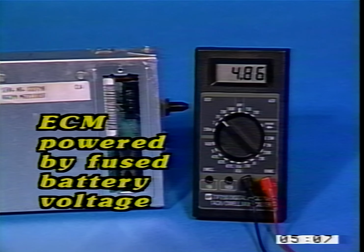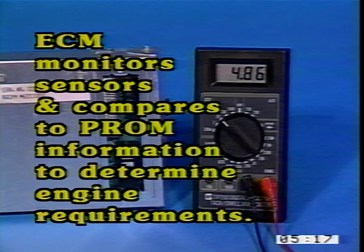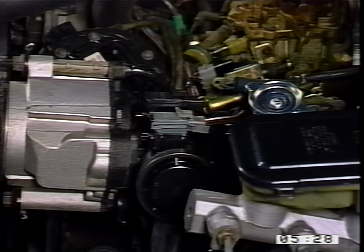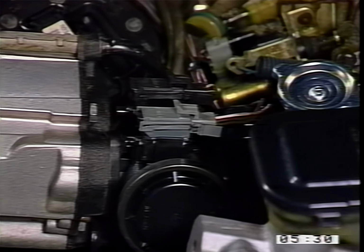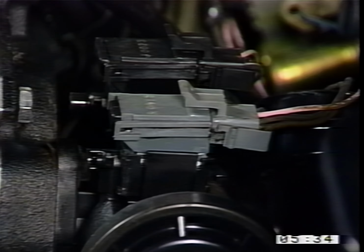The ECM is powered by fused battery voltage. When the ECM is powered, it supplies a regulated 5 volts, or reference voltage, to its sensors. The ECM monitors returning sensor signals and compares these signals to its PROM information in order to determine engine operating requirements. The ECM provides ground to individual 12-volt powered under-the-hood solenoids based on both the PROM and sensor information.